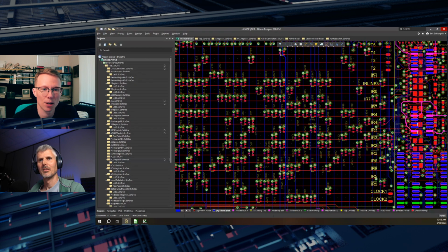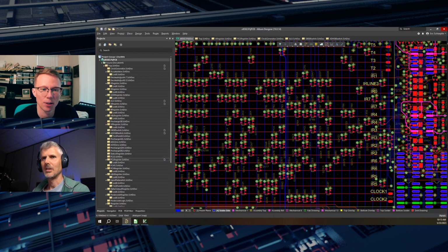The problem was I didn't know what the test coverage would be, and so I ended up taking the Visual 6502 JavaScript and hacking it together with another script that would go through and disable each transistor one at a time in the design. It did it twice for each transistor. It would make the transistor either stuck on or stuck off. And then it would run the entire validation suite to see if it detected that broken transistor. Check that it actually failed. And so by taking the percentage of transistors that were detected versus the total number of transistors, I was able to confirm that test coverage was around 80% after I made some improvements to the program.